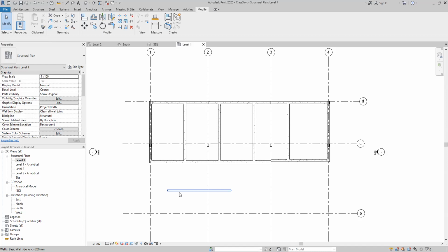To understand this one, I go back and explain something about survey point and base point. What's the difference between survey point and base point? Normally in practice, structural engineers don't use a survey point much, but architects normally use this one. But I'll explain it to you, and if you want, you can use it. If you use a survey point, you can pick up your coordinate. Actually, no need to calculate. On the screen or on the element, you can pick up your coordinate. Let's say if you want to set out one column, normally what we do is we set out the grid lines, right?